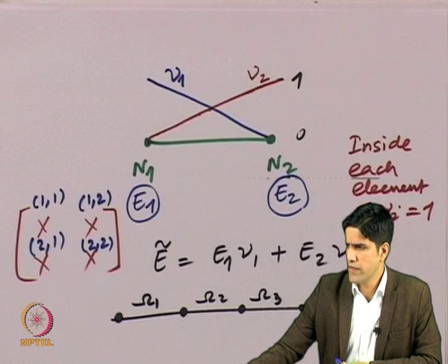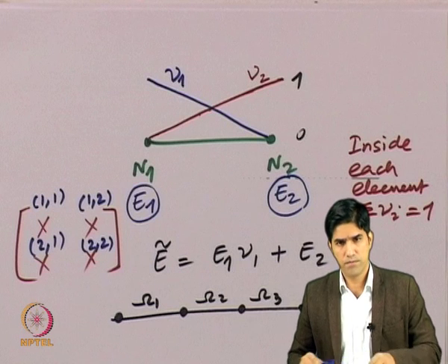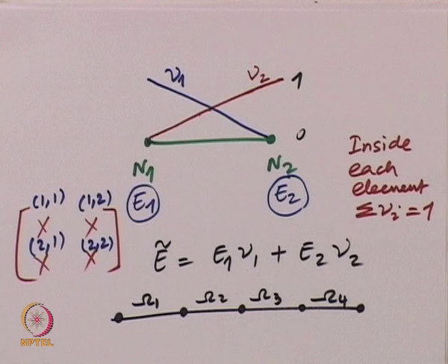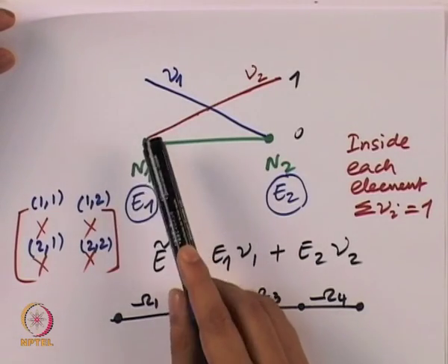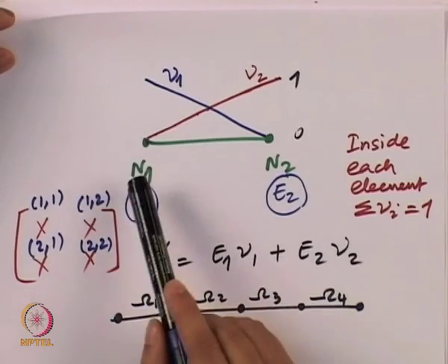So now we have looked into a very simple case for the basis function. In the one dimensional case, as I have explained here, what you see here is a linear interpolating function whose values, or in other words whose degrees of freedom inside the element, are in 2 points.